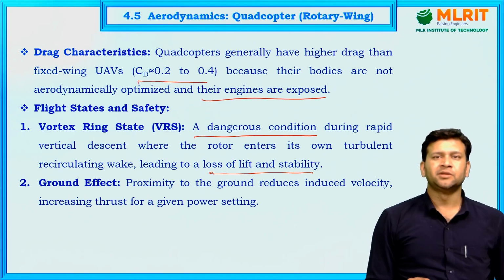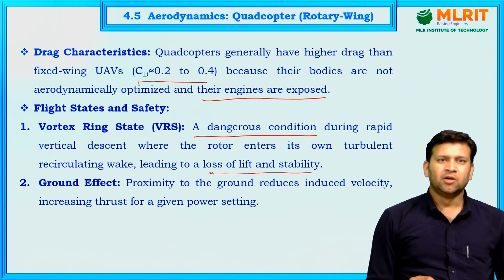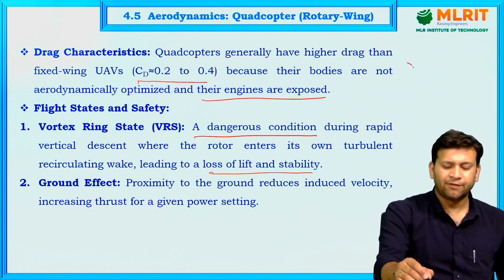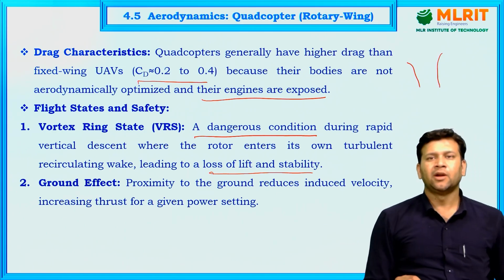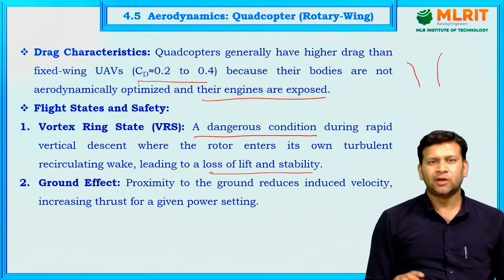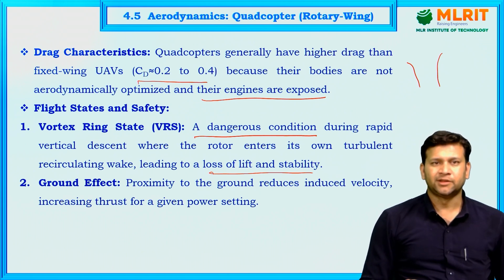It's a condition that occurs when these quadcopters are moving up or coming down vertically. When it comes down, it creates a lot of wake, and when those propellers interact with that wake, it will create this vortex ring state.